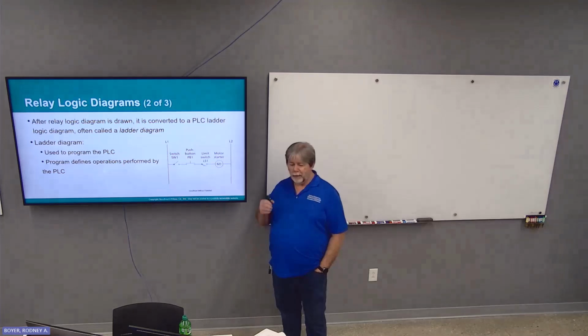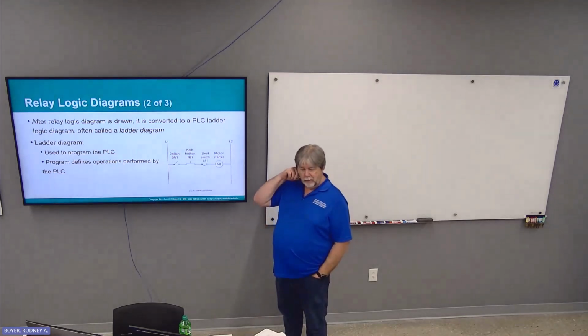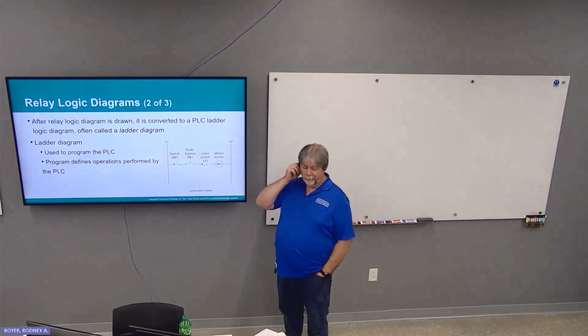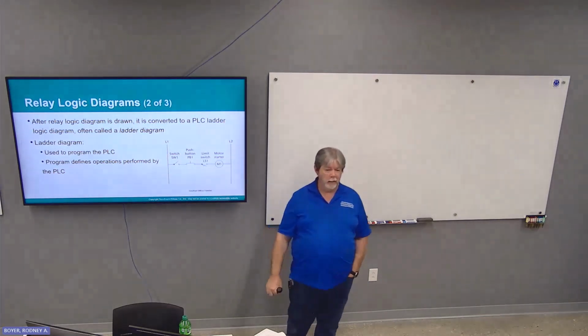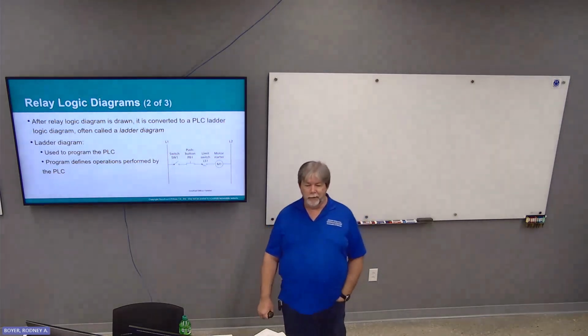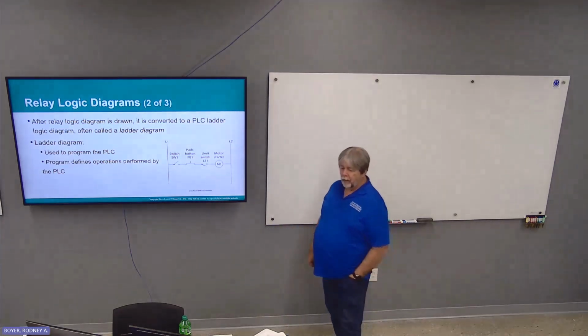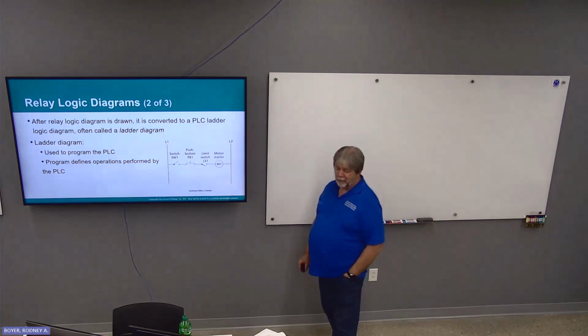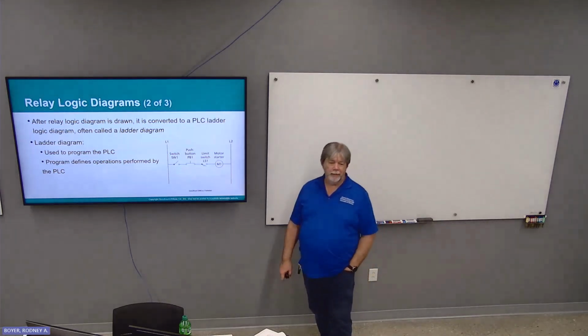After the relay logic diagram is drawn, convert it to a PLC ladder logic, often called a ladder diagram, LLD, ladder logic diagram, as opposed to RLD, relay logic diagram. Ladder diagram is used to program the PLC, and the program defines the operations performed by the PLC.